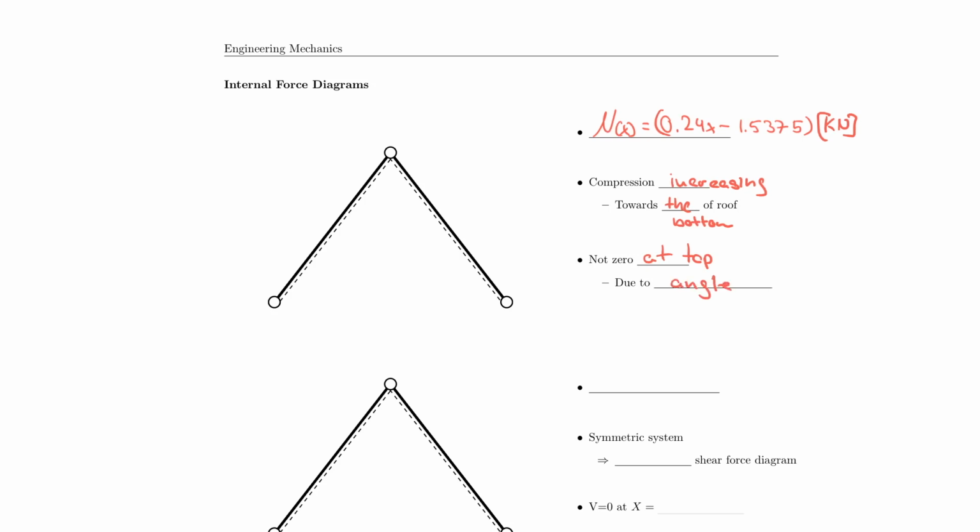So that hasn't changed. In fact, if you paid very close attention, you see that this equation, except that the numbers are a little bit different, has the same concept as we had for the self-weight. And this is on purpose here for educational reasons, right? I used the 500 and the 500. Actually, any value would have made the form of the equation the same, no matter what I would have chosen. But since we used 500 for snow load and 500 for self-weight, you see that here for snow load, you actually end up with smaller factors now. And that is because the snow load is distributed over the footprint, and the self-weight actually was acting over the entire length of the beam, so that made that more intense.